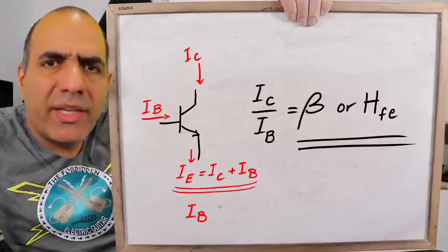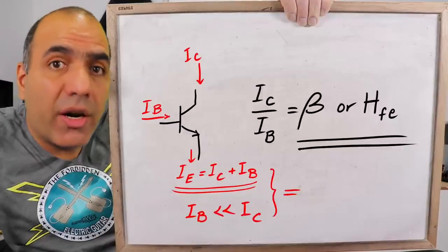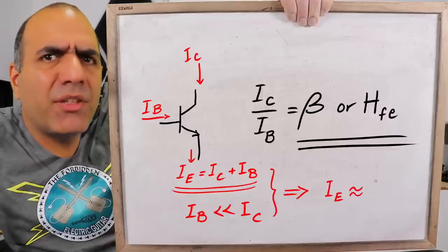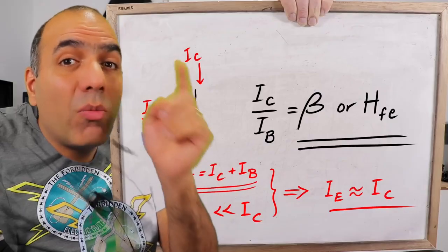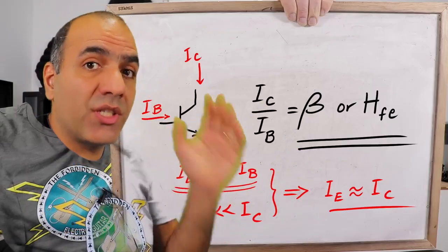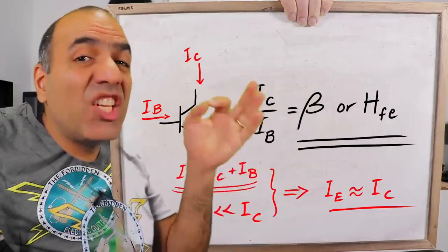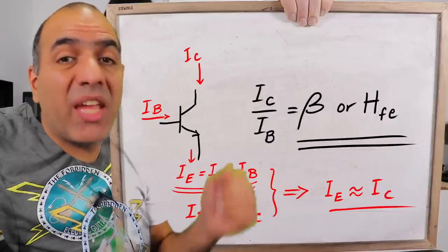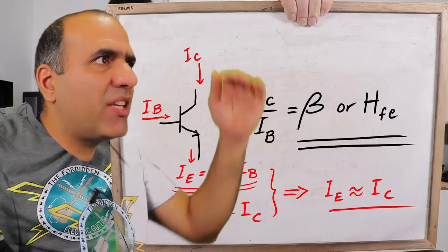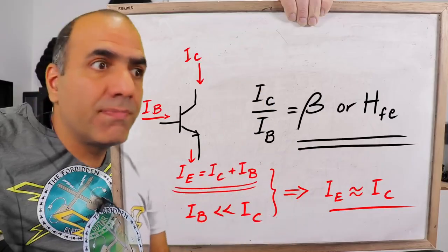But with the base current being much smaller than the collector current, we often assume emitter and collector currents are equal. But this beta thing is only almost constant if the transistor is on and is in active region. What is active region, you ask? Well, the behavior of the transistor changes based on the collector-emitter voltage. Let's measure.